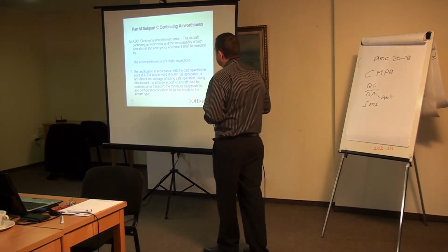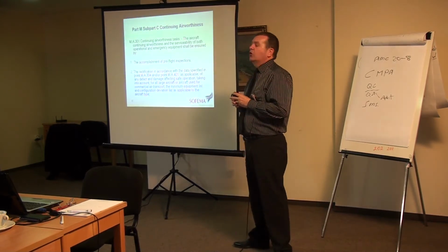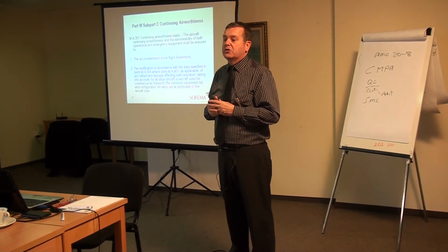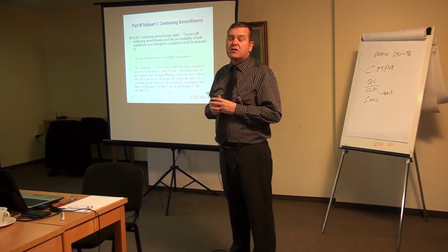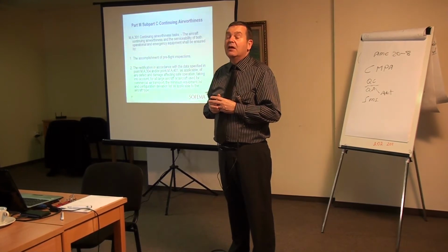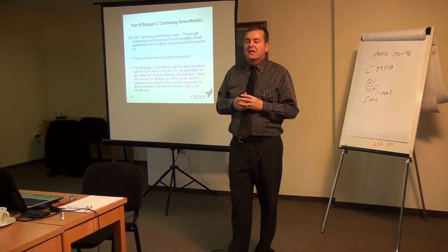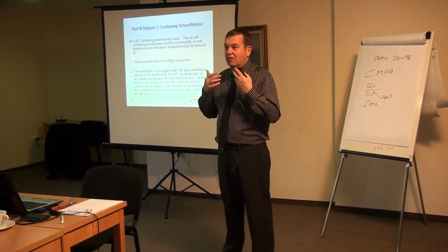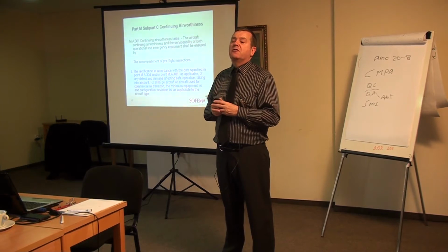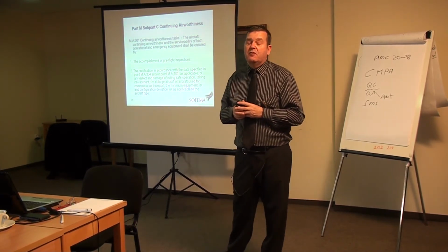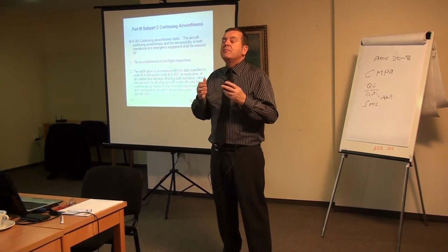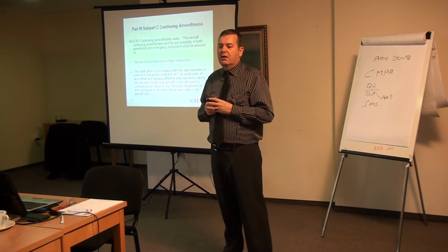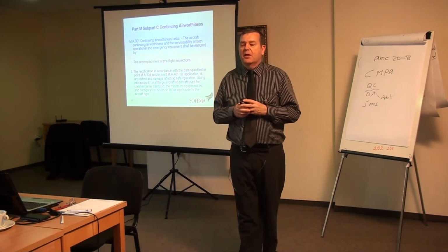In addition, we talk about the accomplishment of pre-flight inspection. What is a pre-flight inspection? Well, it's not a certifying inspection. A pre-flight inspection is an inspection of the integrity of the aircraft and the fact that the aircraft is good for its flight. But it's not a certifying inspection. Typically, flight crew carry out a pre-flight inspection. Other people can be trained to carry out a pre-flight inspection.